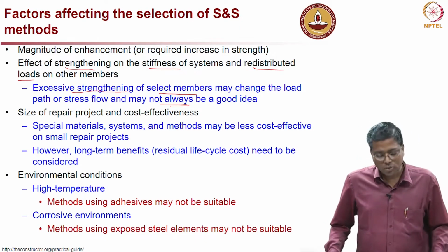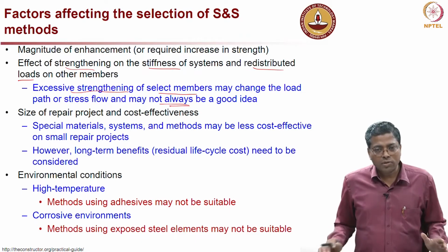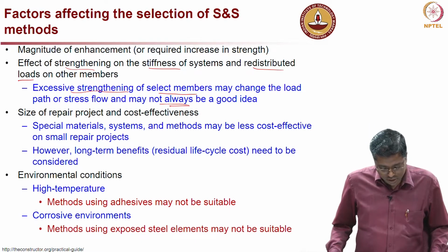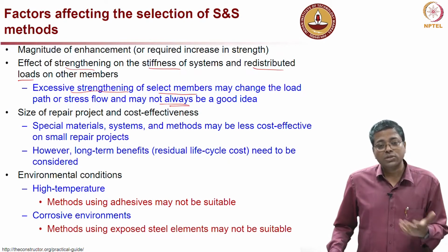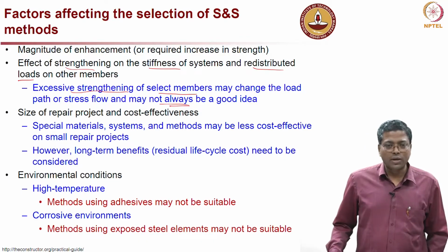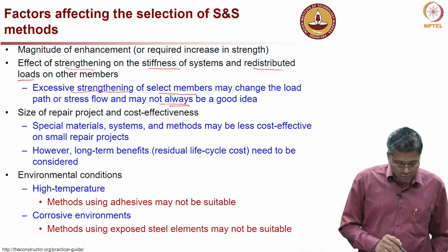These things happen. So, it is very important to make sure that such things are not happening, and whatever grade of steel is recommended by the engineers must be used. If you want to change it, it should be checked again for brittleness and all the structural behavioral aspects.